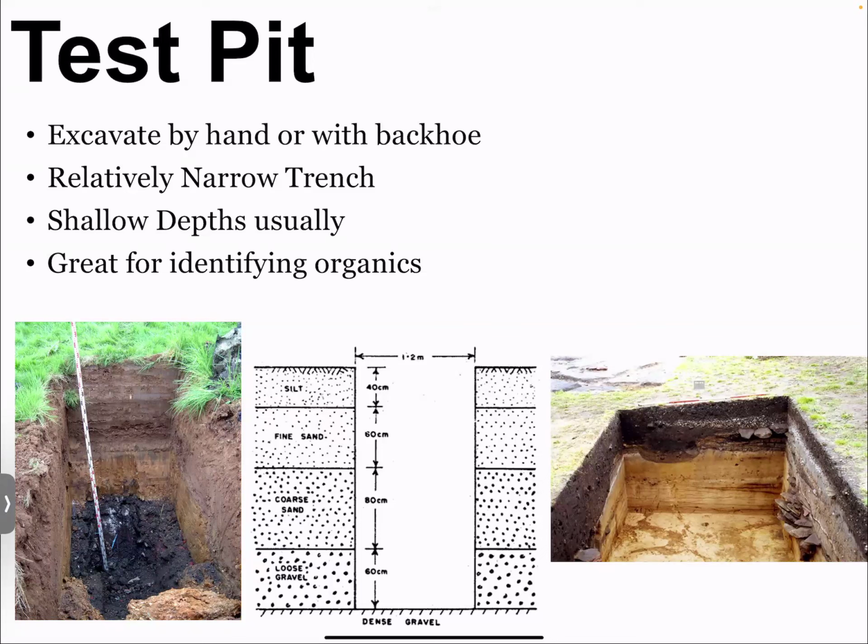The picture on the right is more of a nice looking archaeological, or whatever that word is, dig where they do all these nice little cuts. Most of the time, the engineer would just come out with a backhoe and figure that out. Obviously, limitations are known here, right? There are shallow depths. You can't really go too deep. If it's really muddy, it might be hard to get a backhoe back there, or you don't want the excavator to get stuck. But it's really good for identifying organics.